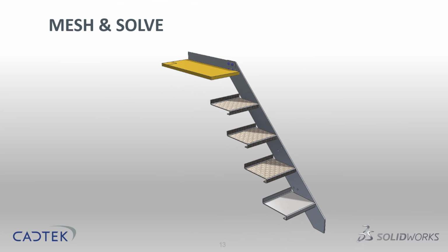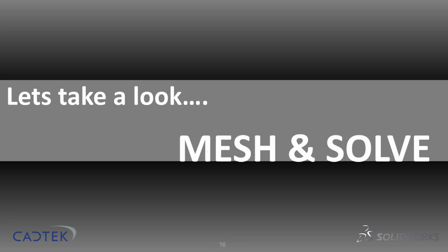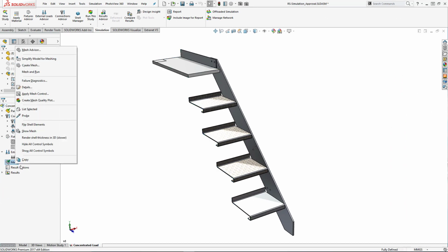Before the software can solve this puzzle, it needs to actually break the calculations down into lots of little pieces. This is called meshing. Now thankfully there's not really much we need to do apart from just to mesh and run these results. So let's just show you that back in SolidWorks. Now we could actually skip the mesh stage completely and just click on mesh and run, and it will just do it, take the default settings.